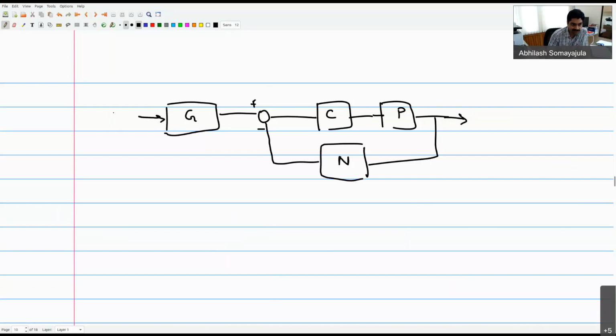And this is where we give that so-called joystick or keyboard or some other methods of inputs to our system, correct? Then we basically convert this into a set of desired trajectories. That is where you get the so-called desired trajectories, which your control system, if it is doing a good job and you have a good navigation system which is able to measure back the sensor information properly, you expect the output here to be equal to eta d.